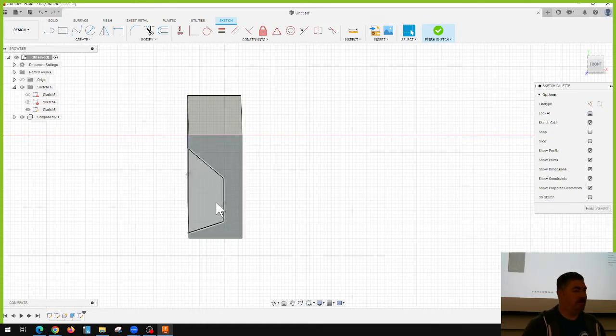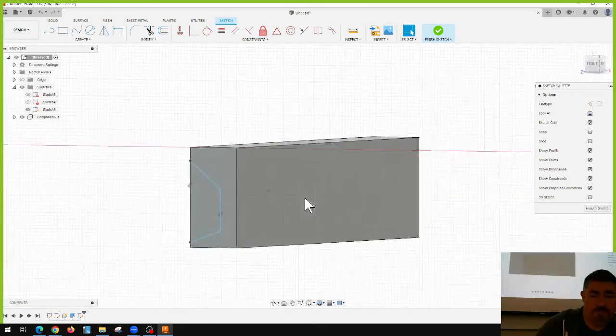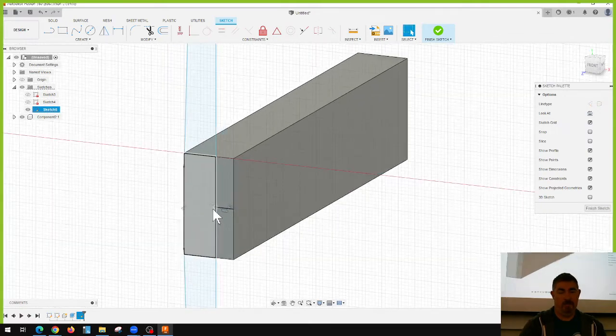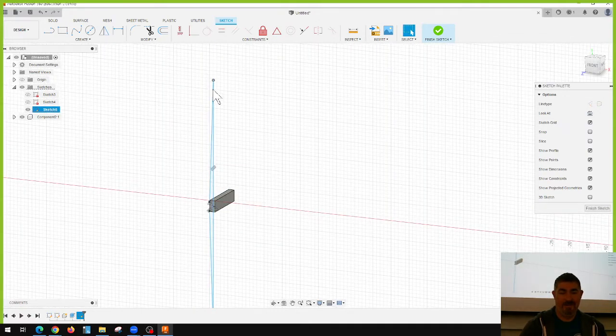I need to center this and make it even, right? How can I do that? Dimensions. 4 dimensions. How can I make this centered and make these two angles the same? What? Draw a line from the midpoint of there to the midpoint of there. Then make that horizontal. Did that, so just drag it back and whew. Now the sides are ridiculous. Okay.